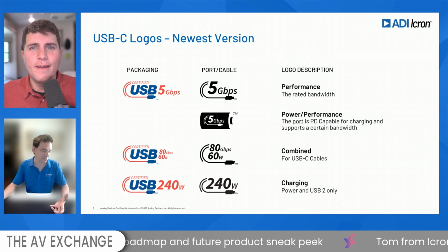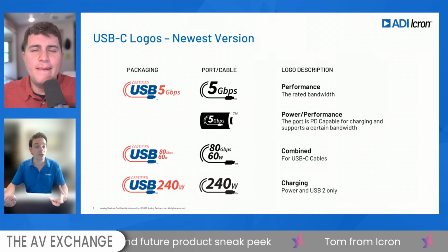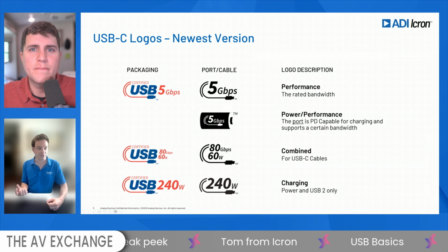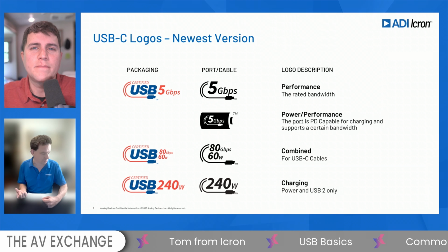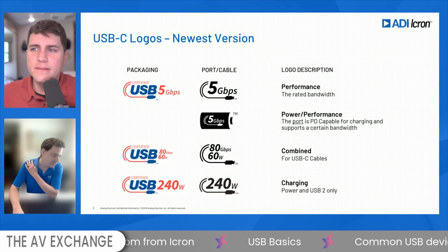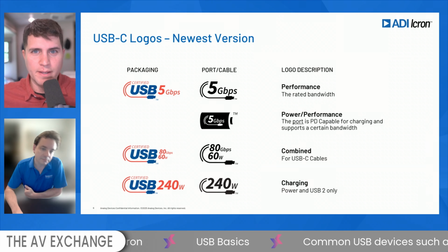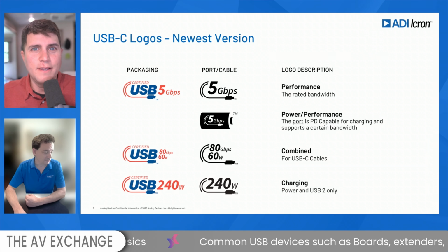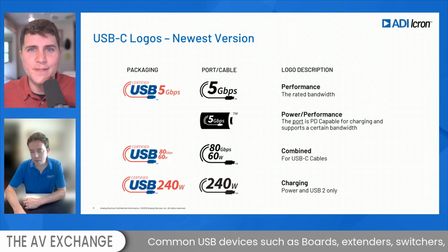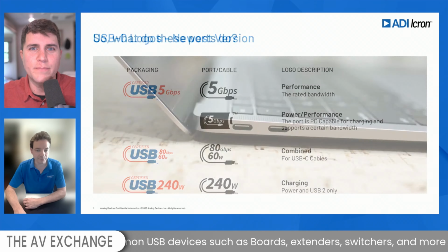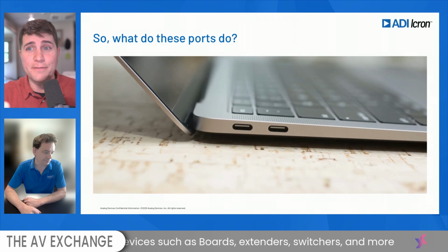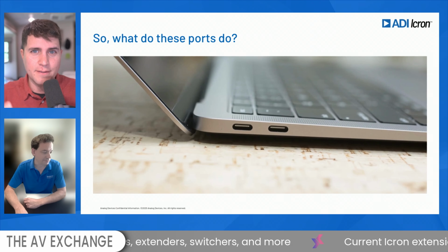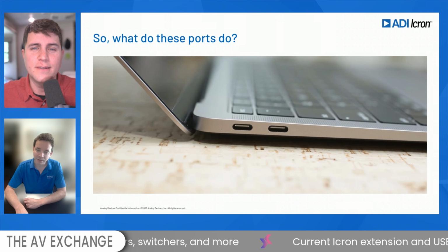Got it. So basically, that just means the conductors are good enough for high speed signaling. And then for the power, the IC inside is going to negotiate up to that wattage, and it's safe to use it for that wattage, basically. At the end of the day, we're talking about data transfer, and there's X amount of bandwidth, and that's what it takes to do it. So it sounds like the answer to Dawson's question is there are some indicators, and they're supposed to be much more clear than they really are because of the changeover that is happening. So I think the safe answer is still to defer to the documentation when that's an option. In the field, this is probably most applicable.